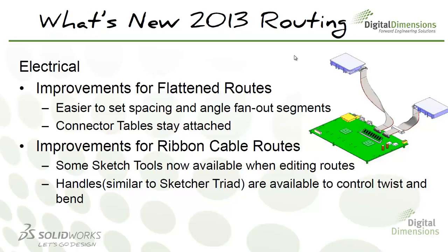And then the other big improvement was when you move a route on a drawing, now the connector tables stay attached. That was something that you'd have to manually move around. That's a nice enhancement that will definitely save you some time when you're trying to show a drawing of an electrical wire route.